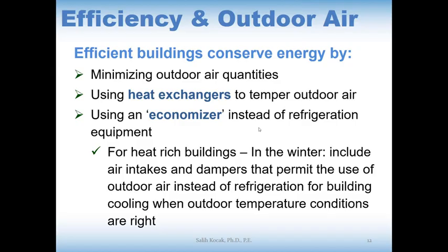If you minimize the outdoor air quantities, that's good to conserve energy. Minimum outdoor air means minimum heating and cooling costs. Tight buildings with carefully controlled ventilation rates can save heating and cooling energy tremendously. Really, it does.